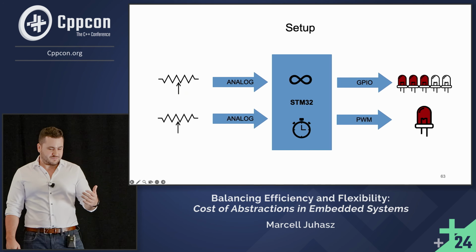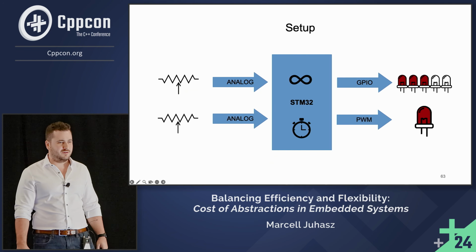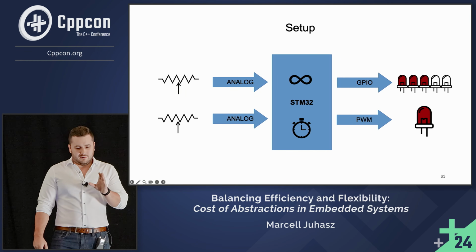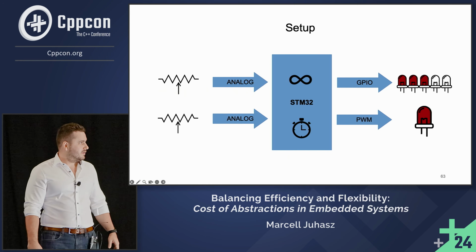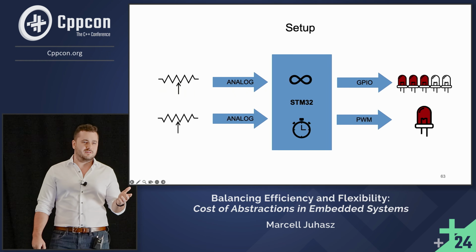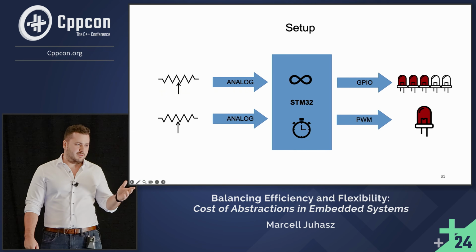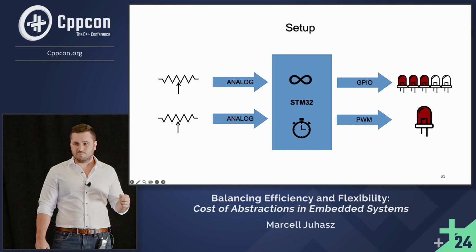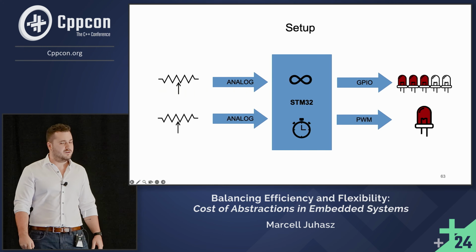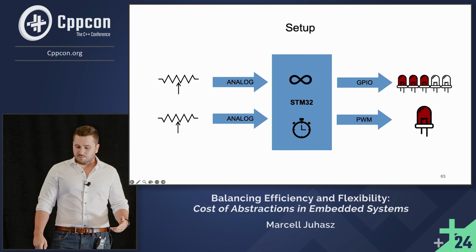So to prove the power of C++, what I did is that I implemented this project on a breadboard. It has an STM32 microcontroller in the middle, and it has 2 analog inputs. Now, in my case, these were just potentiometers so that I could set them by hand. But you can imagine that this could just as well be reading some kind of physical value, such as temperature or humidity. As for the output, I hooked up some LEDs.